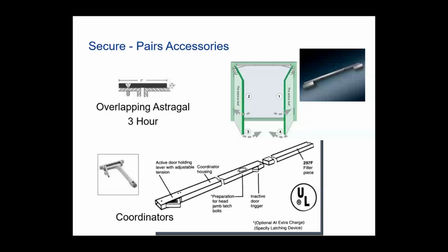This is used whenever you have a cylindrical lock, mortise exit device, or mortise lock. It will not be used whenever you have vertical rods or concealed vertical rods, as those openings aren't interacting with each other. They are independent of each other. So you're able to depress the rim device or the push pad on the device to operate those doors.